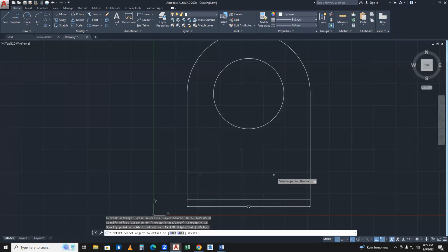Next step, what do you do? So that's another horizontal line on the top with the length of 50. So we can draw that also. So we can get the vertical offset, 10 from the 60 vertical line. And also we can do this one also. This horizontal line is also the same 15. So I have chosen that and then enter. So I'm choosing this side, so the 15 offset is done.